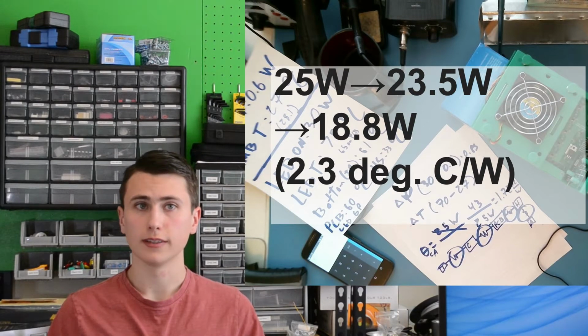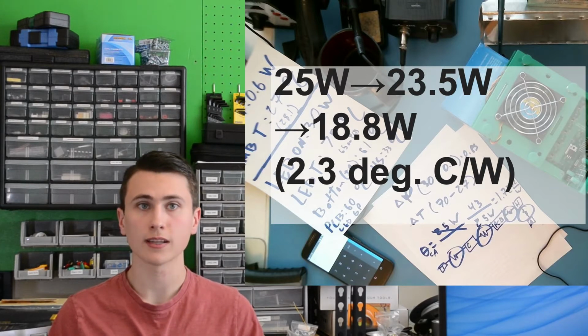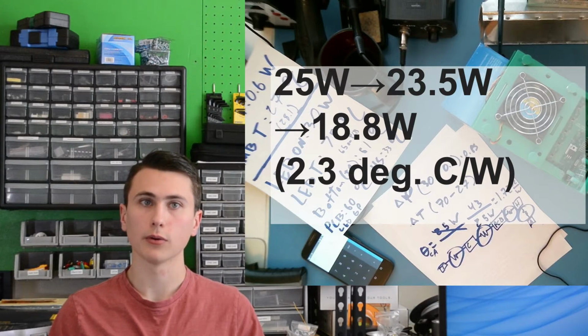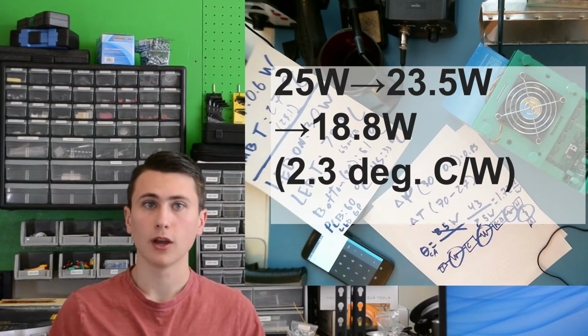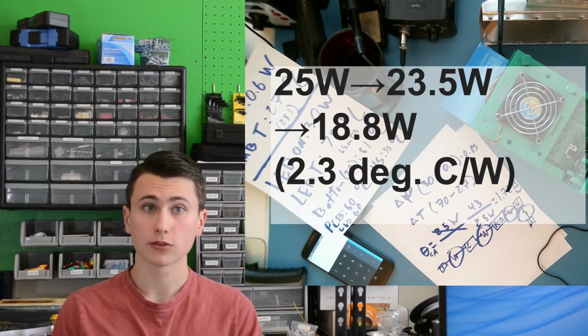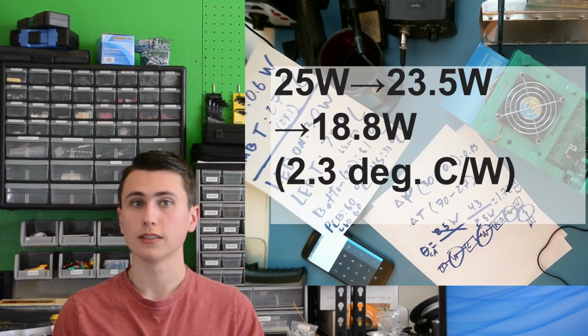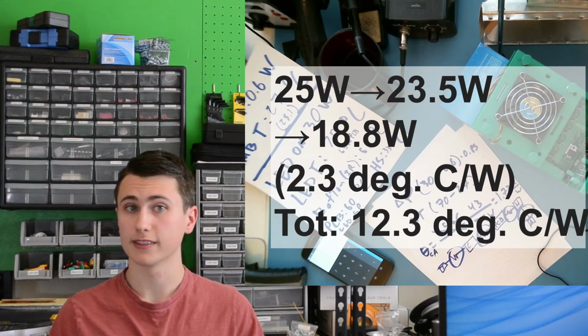Keeping in mind that each LED has a junction to case thermal resistance of about 10 degrees Celsius per watt, and each LED is dissipating about 1/30th of the total power, the junction of each LED should be about 6 degrees warmer than the case, so around 76 degrees C. With all of these factors considered, the total thermal resistance of the system from LED junction to ambient air is approximately 12.3 degrees Celsius per watt. That's a far cry from the 1.72 we will come up with on Saturday.